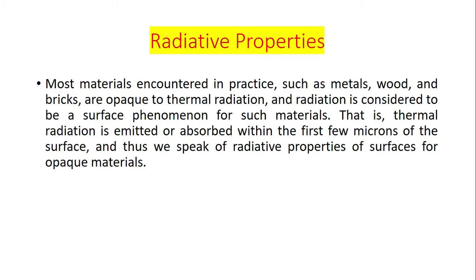Thermal radiation is emitted or absorbed within the first few microns of the surface. So we speak of the radiative properties of surfaces for opaque materials. Those materials which are not transparent, we only consider the radiative properties for the surfaces of such non-transparent or opaque materials.